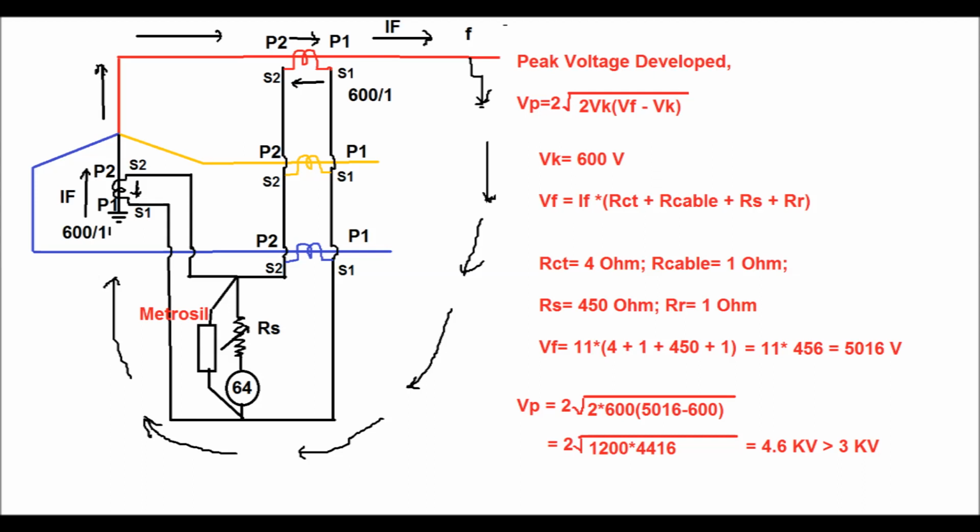So friends, now you understand why the Metrosil is used in case of REF protection, and how to calculate whether the Metrosil is required or not during maximum through-fault condition, that is the development of the peak voltage across the relay circuit.